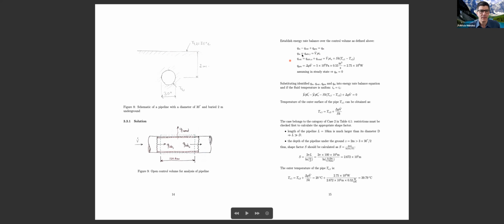And Q generated. Now, look at this control volume. Inside there is heat generation, and the heat generation is something you already know. I'm not going to be testing you on that, because this is heat transfer, not fluid mechanics. But the energy loss is the pressure loss times the volumetric flow. That gives us watts, and this is the energy generated.